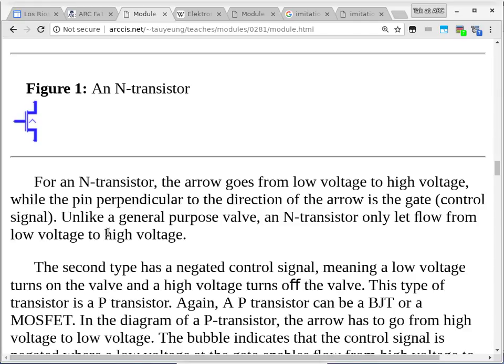It does not. It's only the charge. And that's why you see there's no actual connection to the rest. So it's basically the presence or the absence of a positive charge, but there's no quote unquote actual current going through the gate. It's because this is called a field effect transistor, or FET, instead of a BJT, bipolar junction transistor. So it's a different type of transistor. But as far as we are concerned, we just need to know charge at the gate controls the state of the transistor.